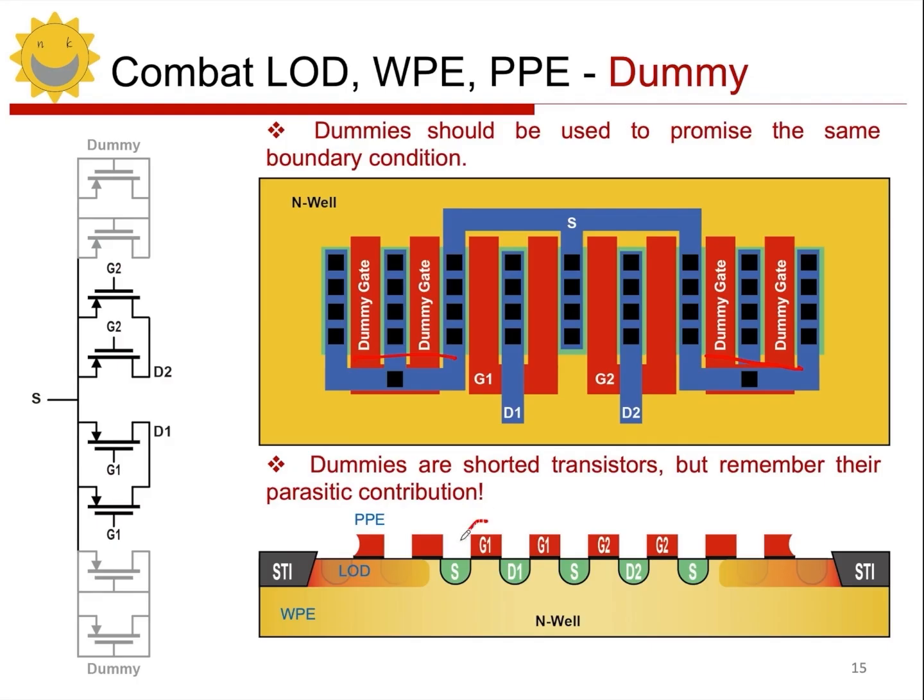Let's look at this area. It is the core area of our two transistors, right? The core area. So if we want the two transistors to be more consistent, we actually have to protect the core area. So how to do it? Let's take a look at the stress problem of STI. Well, on both sides of the core area, we put dummy transistors, right? So you can see that the STI is running here, right? This is the STI. If you don't have dummy transistors, this position, well, this STI will extend here, right?